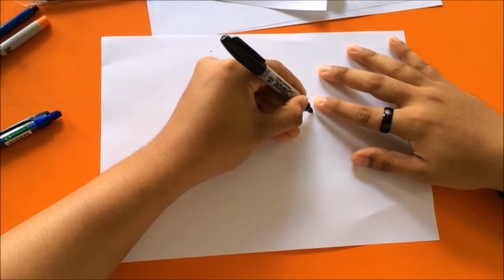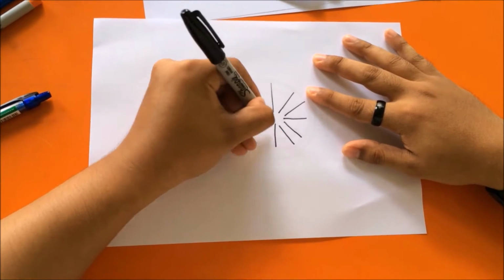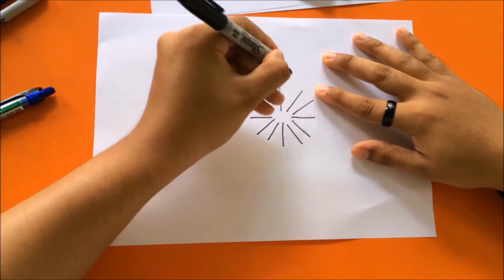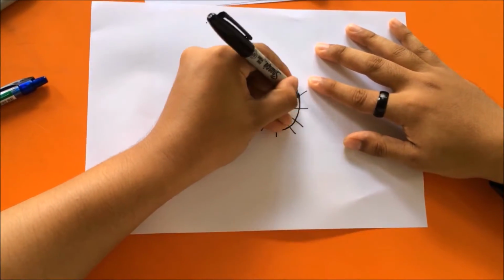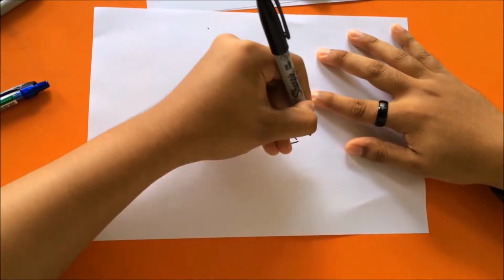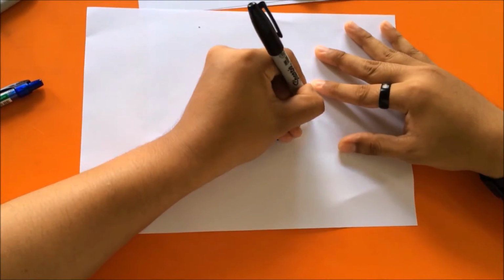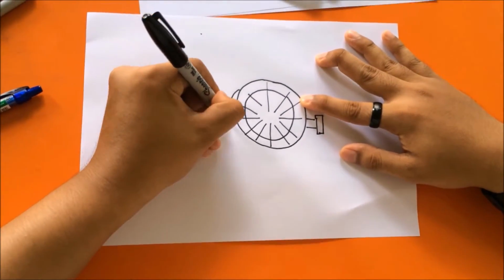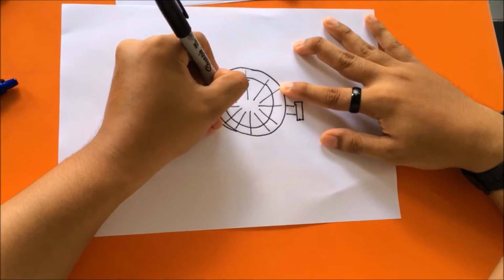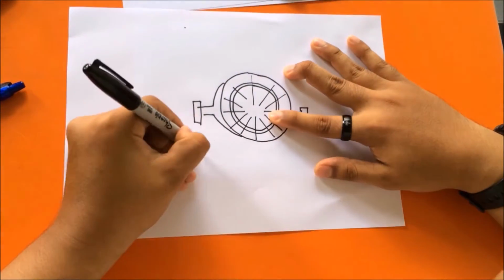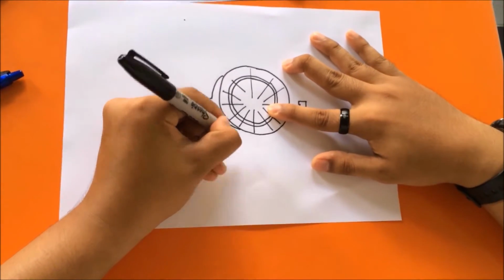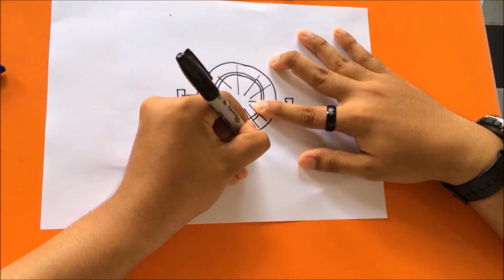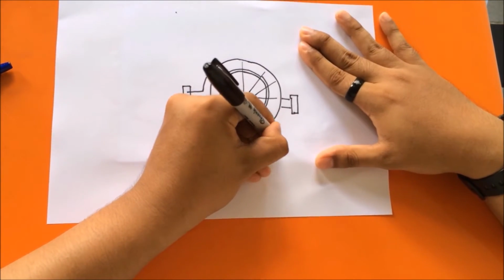Thirdly is the vacuum pump. If vacuum is lost during distillation, the temperature of the feed or batch can increase to the heating medium temperature. Loss of the vacuum can be due to the blockage in the line. This can in turn lead to a seal system with increasing pressure. A failing vacuum pump can have the same effect because the pump is usually sealed. This proves that sealing the vacuum pump is essential to the safety of the process.